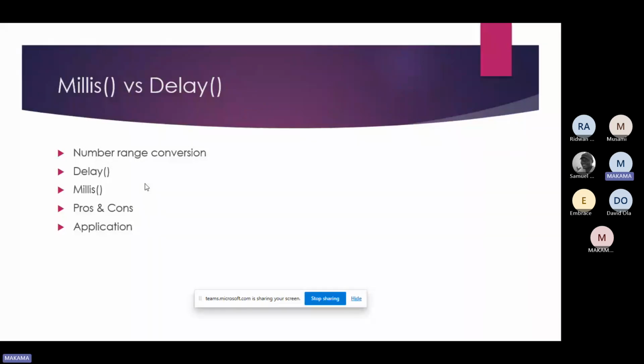That is when you want to have a highly efficient embedded system. You can ignore the delay function, because sometimes in your project you don't need it. Once you call the delay, it's not that you want to pause the whole system. It's just that you want to pause an LED alone, or a potentiometer alone, not the whole system. But you don't have a choice, because it's the delay that they give you. You have to use it.